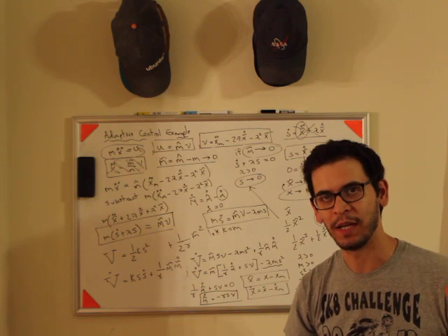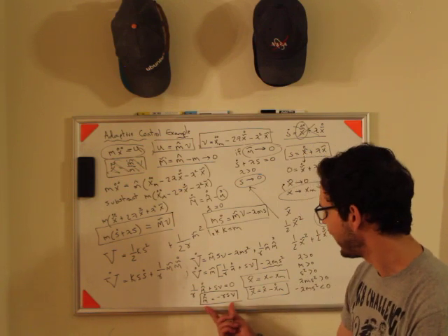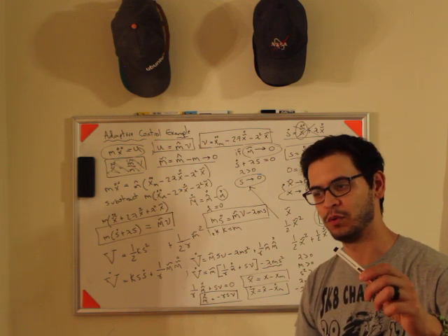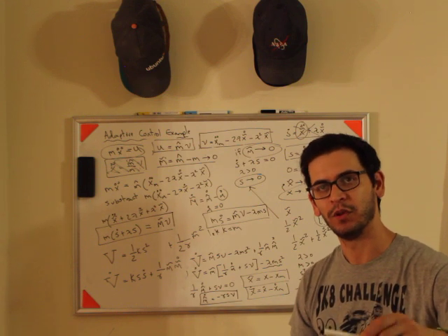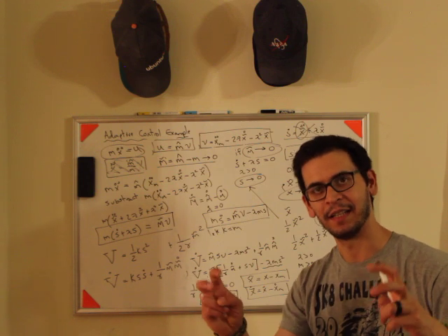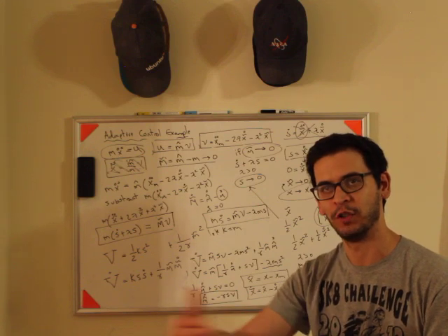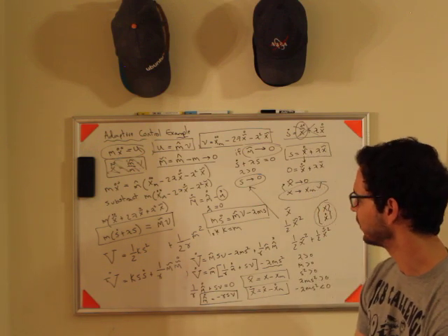If you make your reference dynamics just a step, m hat won't have enough time to catch up to your actual mass. So you need to put in a sine wave to excite the dynamics and actually get m hat to fully track your mass, okay?